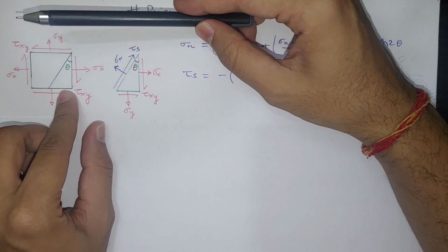Now the shear stress is acting, you see here, these are the shear stresses, and the opposite two are the complementary ones. Let's say I hold this and I pull this surface down, so there will be shear stress here and here, because I am giving a stress. But to maintain this element in equilibrium, the material will generate internal stress in the opposite direction like this. So if I try to rotate this element in the clockwise direction, anti-clockwise stresses will be generated inside the material, which are called complementary shear stress.